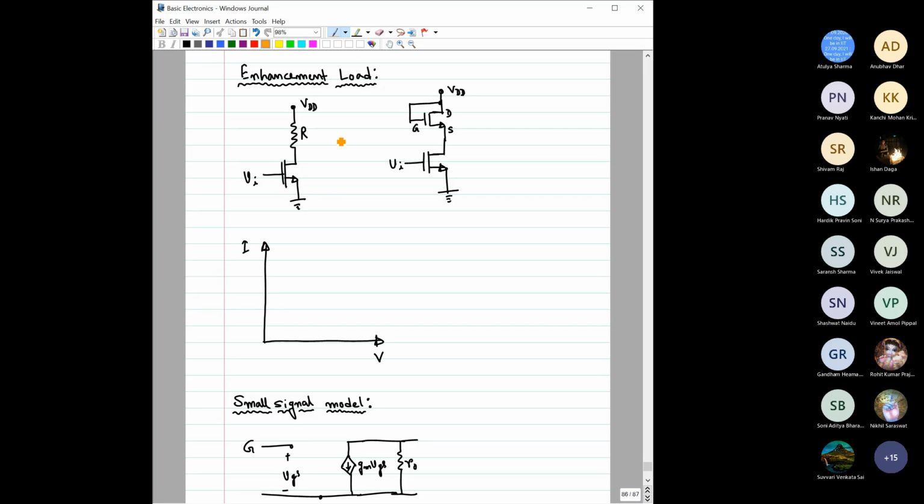So typically in our previous analysis, suppose you have to use a transistor as an amplifier. So this is the VDD supply. You take a transistor, properly bias this gate, and then apply the small signal here. And we connect one resistor here and take the output from here. Everything is fine, right? So this is basically RD. That's all we have been doing so far.